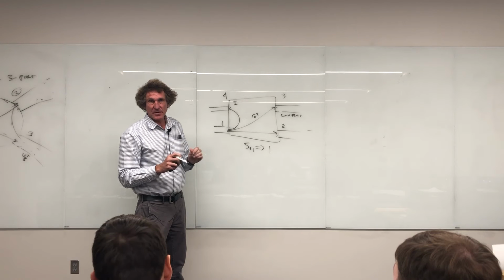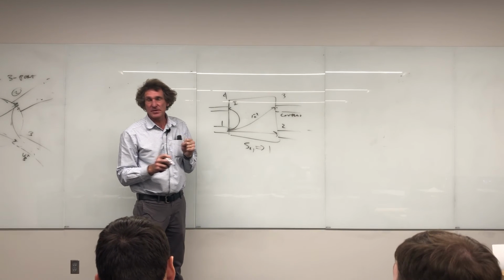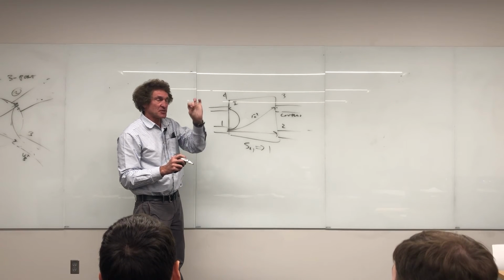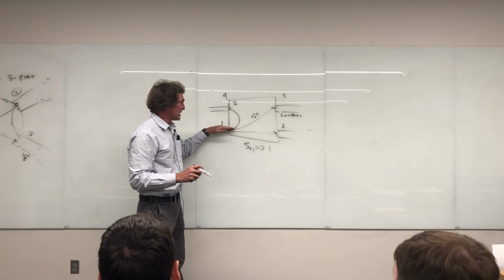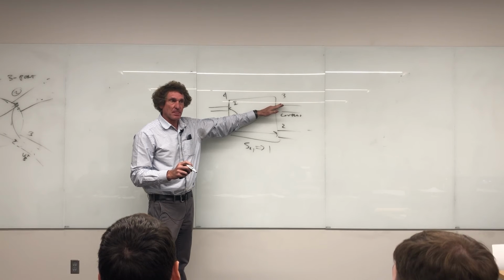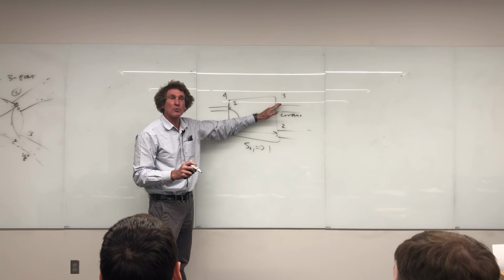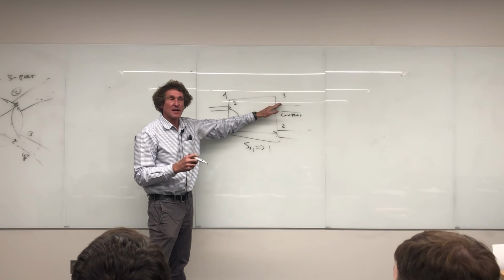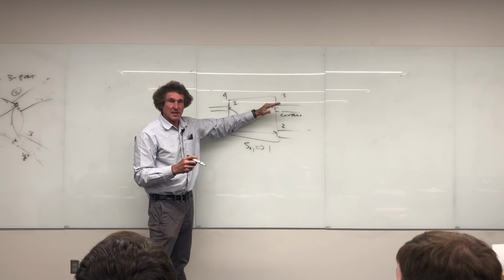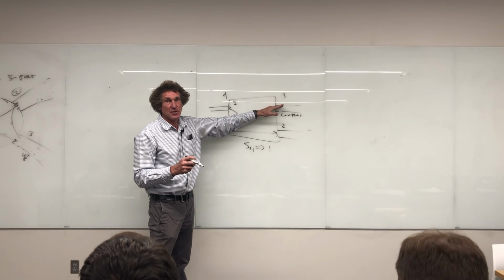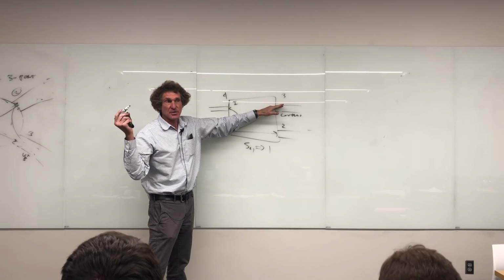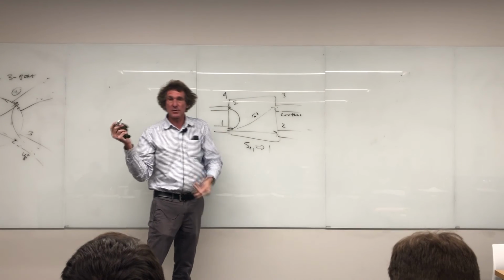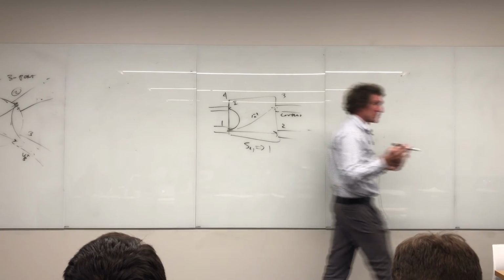Now, mainly what you have to understand is when you're doing very high frequency engineering work, you always want the exact signature of the signal at the time it's sent. And that's why this coupled port becomes important, because that'll be an exact replica of this, only orders of magnitude less. And that way you can do digital signal processing work. You know what a match filter is? You can take this, digitize it, inverse it, and use it for match filtering the signal coming back, and that way you get the exact range. That's beyond this course, but that's what that port's really used for.